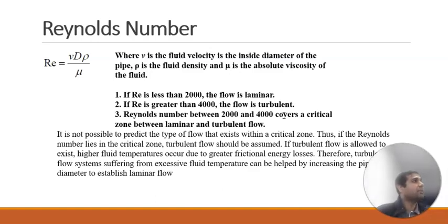Sometimes it's very difficult to calculate or to tell, without doing a prototype, whether the flow is laminar or turbulent, if the value is between 2000 and 4000. So it's extremely difficult. So this is why we have CFD modeling. We do CFD modeling, we test all the cars and the aeroplanes and so on in an air tunnel to find out whether the flow is laminar or turbulent.